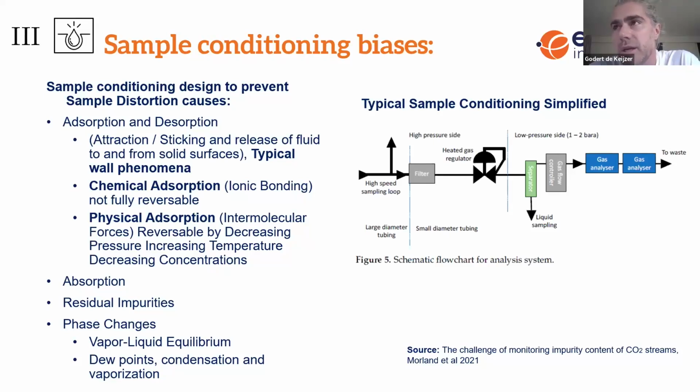And also it's good to recognize that some of these analyzers have filters to protect the analyzer themselves. The fact that they have filters in them means you're filtering out something that you're then also not measuring. So it's very important to be cognizant of these things when considering impurities.